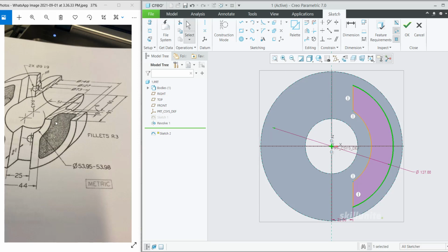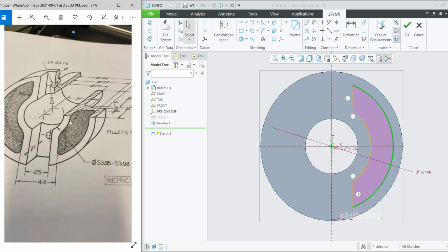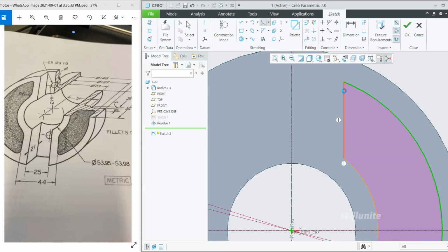And the inner one, you can see it is coming along the same axis of this one. Either you can make it coincident with that one, since already we have a circle, or create a dimension for that. So that is 73. Fine. So then every edge has been filleted with R6. So click on fillet and make the sharpness into blend.